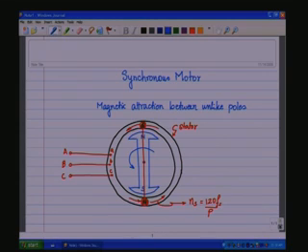So as the stator magnetic field is rotating at speed ns, and as the rotor magnets are also rotating along with it, the speed of the rotor is also going to be ns. So therefore the rotor rotates in synchronism with the rotating stator magnetic field. So this is basically the basic concept, the principle by which the synchronous motor operates.